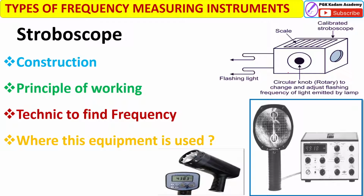What will happen when a reference point on a vibrating body is viewed with a pulsating light generated by the stroboscope? The stroboscope will give the flashing light and it will fall on the vibrating body. So we can see the frequency of the vibrating body. Therefore, the frequency of the vibrating body is read directly from the control panel. The advantage of the stroboscope is that it does not have any contact with the vibrating body. Hence, it is a non-contact type frequency measuring instrument.